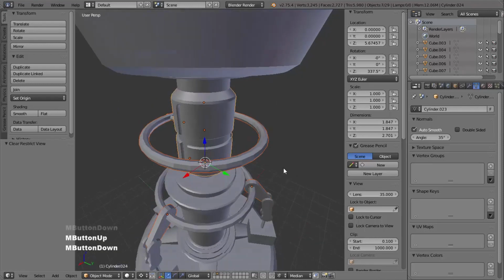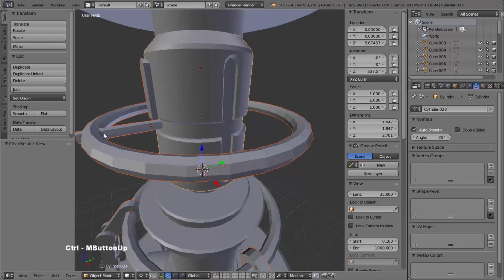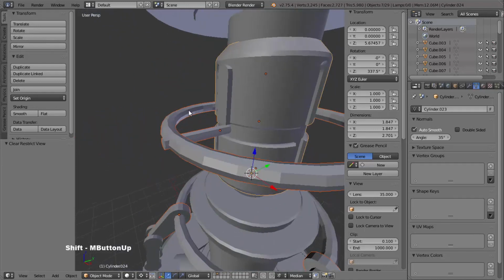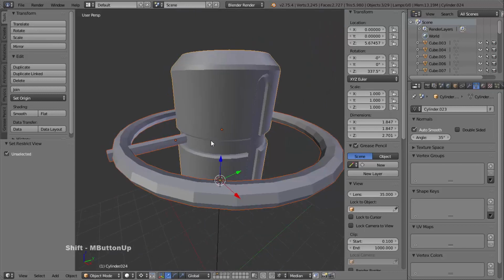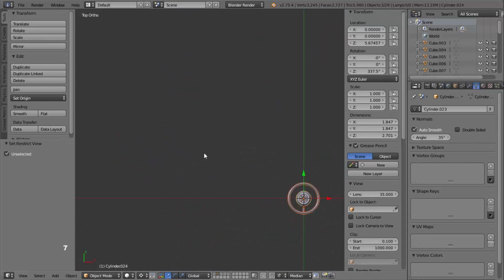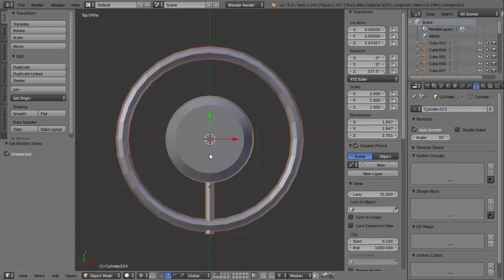all of my objects. And for this next part, I want to use the small cylinder I made earlier as a reference, and I also need the torus and this central column. So I'm going to select those. And this time, I'm not going to use local view, I'm just going to hide the other objects instead with Shift and H. And then I'm going to go into top view and then frame my selection.